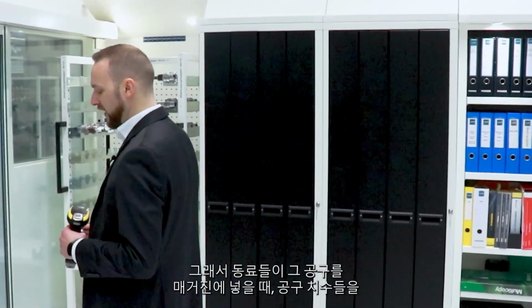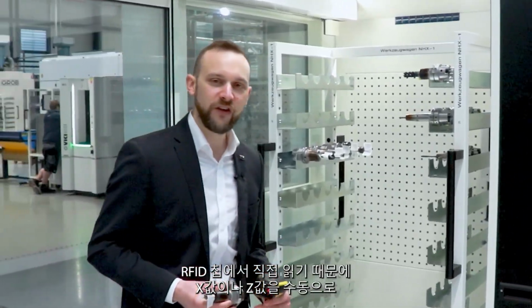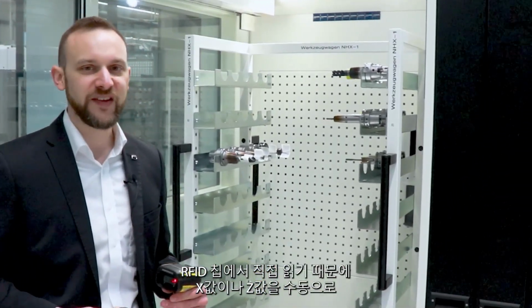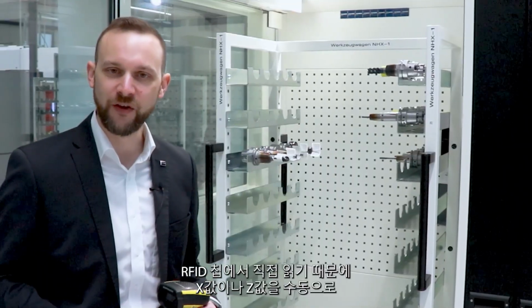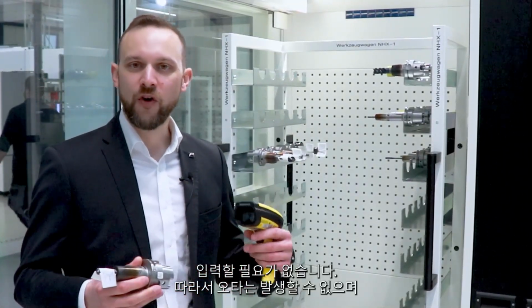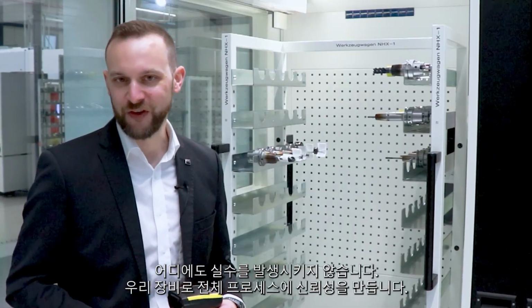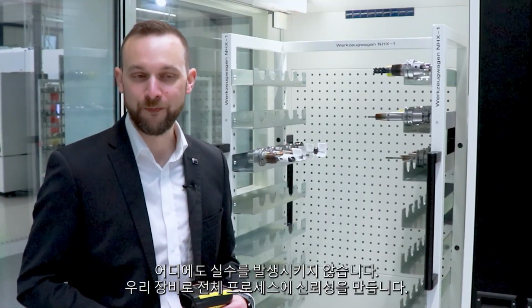So when our colleagues are placing the tool into their tool magazine, they don't need to do any manual typing of X or Z values because it's directly coming from the RFID chip. So no typos can happen, no mistakes, and you have higher process reliability in our machine.